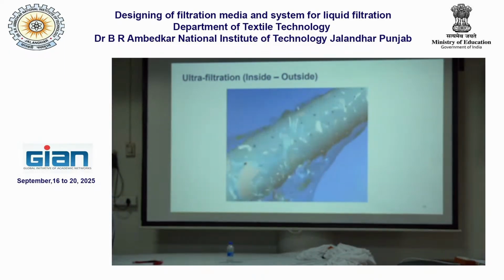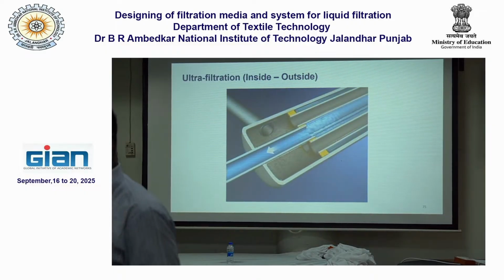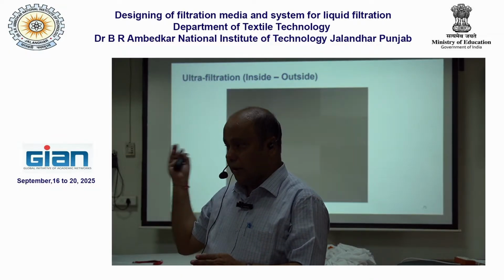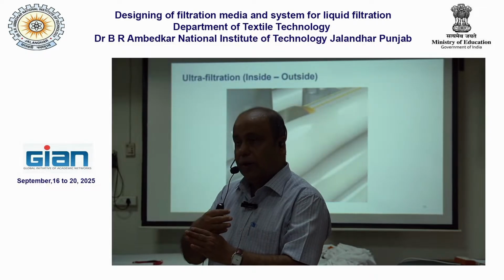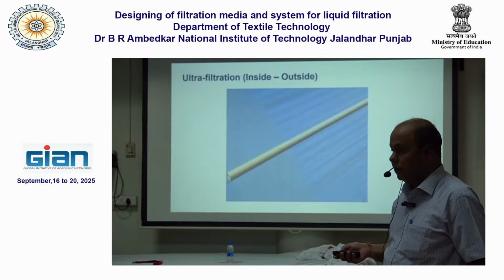Whenever it flows along the media, in the plane of the media, then it is tangential. Whenever it is moving across, like in the drum filter, as I showed you, where the liquid is moving across the filter, then it is a dead end filter.